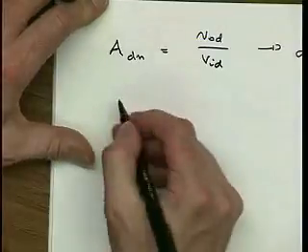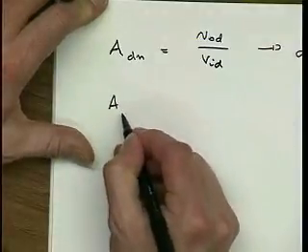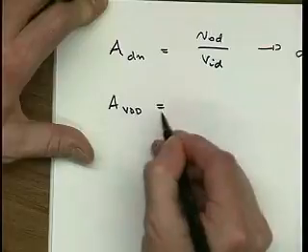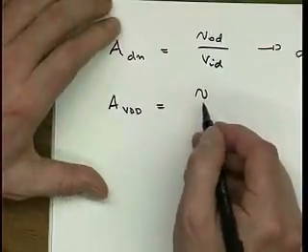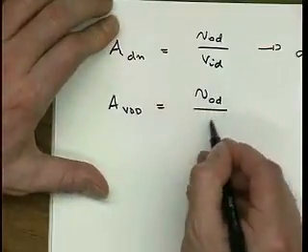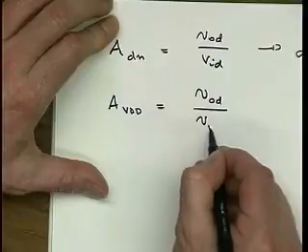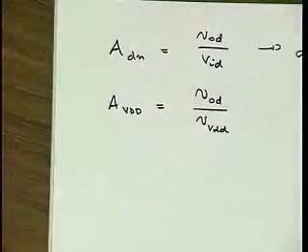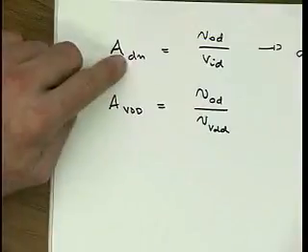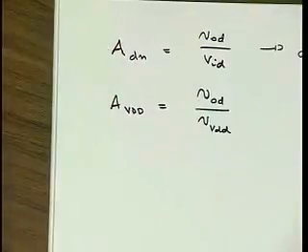Right? Then we also have the gain A VDD, that is the gain VO differential divided by VDD. Actually, how do you measure this thing? Exactly the same way as you measure the differential voltage gain of the amplifier, except that your stimulus is not hooked to the input of the amplifier, but to the supply.